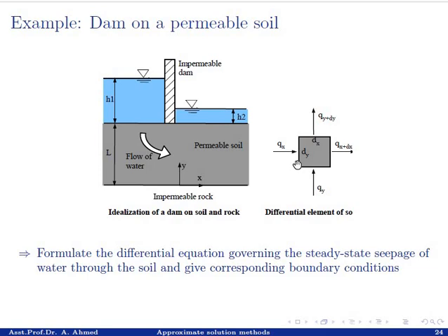Then we can say that the total flow into the differential element must be equal to the total outflow from the differential element, right? So let's say Qx denotes the flow in the x direction at the left end, and Qx plus dx is the flow at the right end. Similarly, Qy and Qy plus dy is the flow at each face in the y direction.